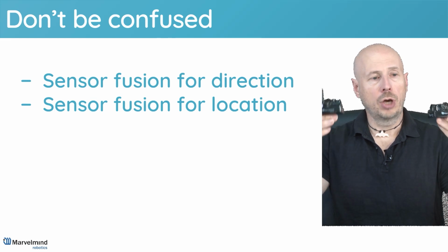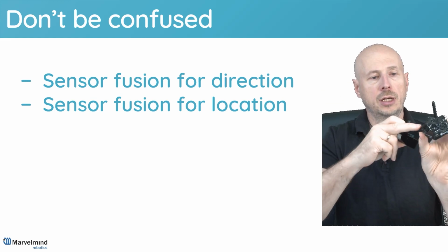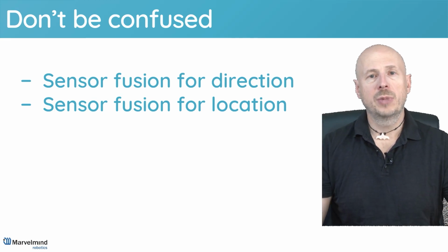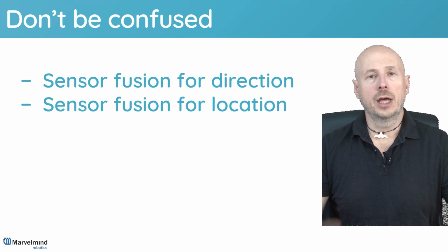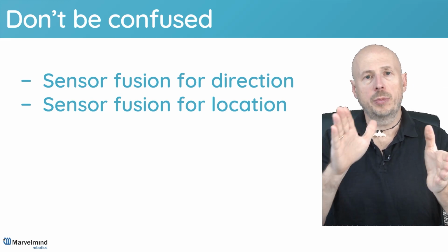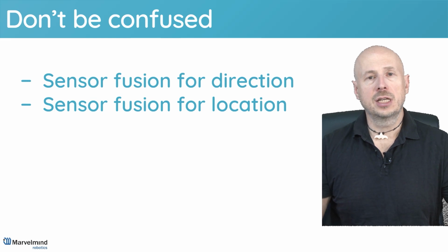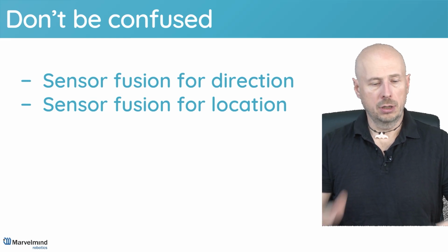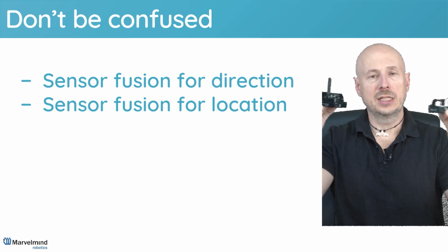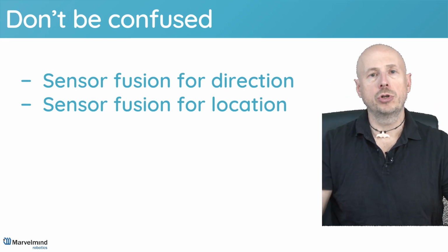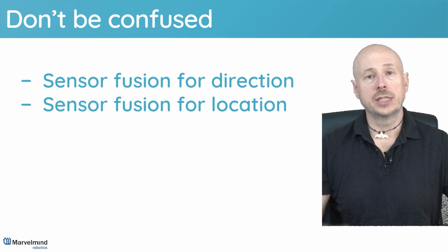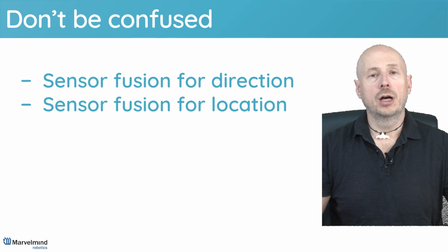So once again, you have 2 beacons. Beacons are connected by 2 wires, so the data is streamed. One of these beacons is the master. The master is calculating their angular position. The master is aware of their location, and the master is capable of precisely sensor fusing their direction, which is calculated based on ultrasound, basically based on the location of each of these points, and the IMU, in this case the gyroscope.